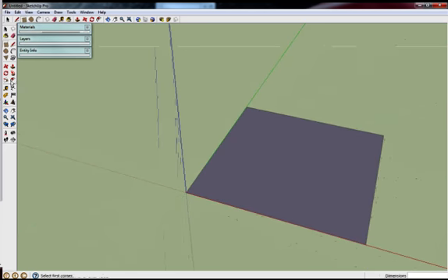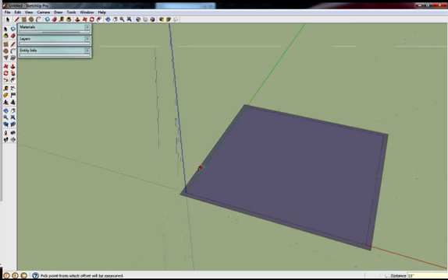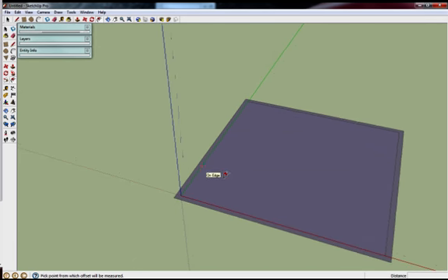Now let's get our offset tool, the F key on the keyboard, so we can make our outside walls. We'll use an offset of 13 inches as modern wall thicknesses are increasing to make the homes more energy efficient.